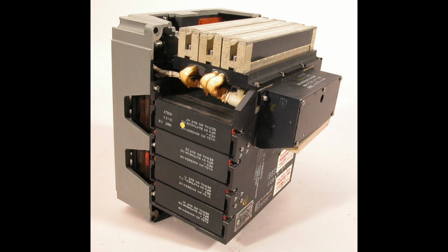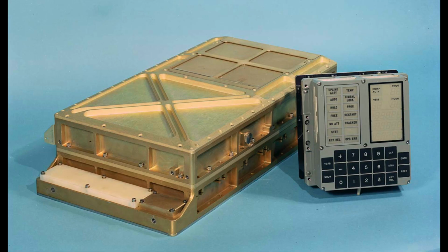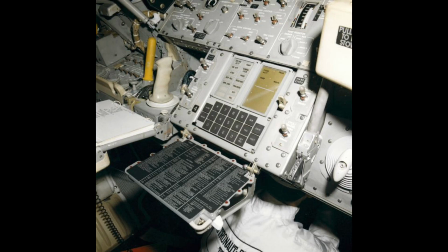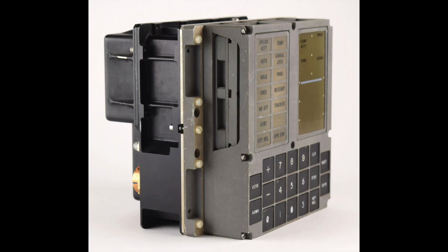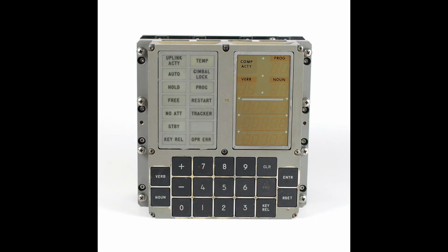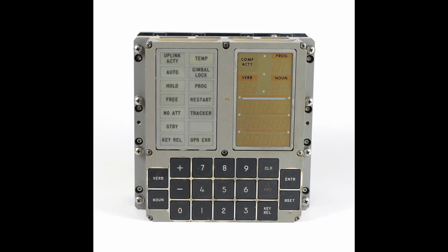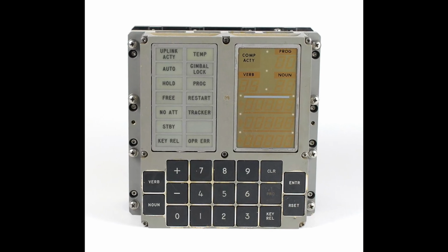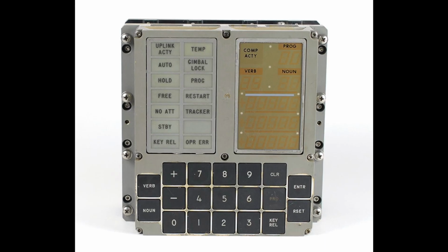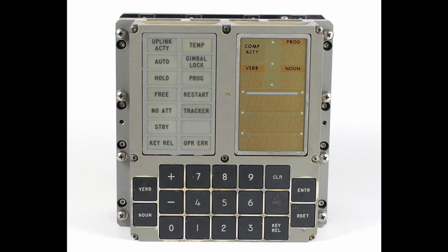The Block 1 DSKY has no back shell, so you can see how it's made of individual electronic modules plugged into a chassis, very much like the rest of the Apollo guidance computer construction. But the DSKY you are most likely familiar with is the Block 2 revision. It is the one that was flown in all the manned missions. It is a much more involved hermetically sealed design, like the rest of the Block 2 electronics. It has a hermetic backshell enclosure, and it also has a much improved illuminated keyboard, also hermetic. But foremost, it features the large single-pane electroluminescent indicator, the iconic display we are trying to relight here.